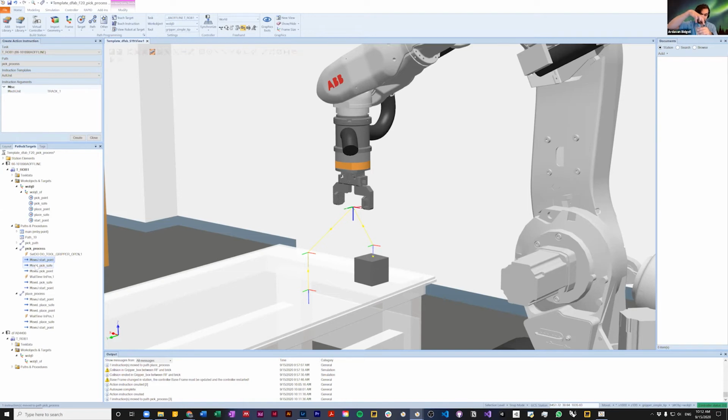So when you get to the place that you want to grab the object, it has this action available. So I put one gripper open at the beginning of the workflow just to clean up everything, make sure that our gripper is open. And then after that 1 second wait, I want to make sure that I'm closing the gripper. So I come back here, I again insert an action. It's again that set DO. And this time, the same thing.